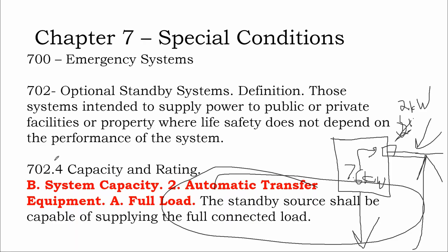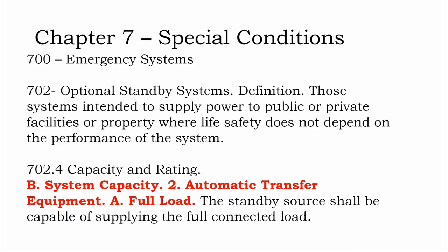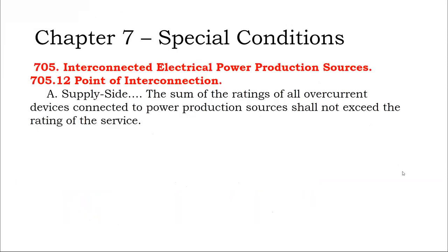That does leave a little bit of gray area for interpretation, in terms of what if you actively manage your devices to put them into an emergency mode setting? But a rigid inspector could say, no, if your battery solar system is not rated to supply a 200 amp service, we want you to use a critical load panel.